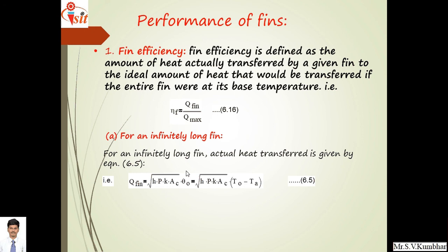So we will see fin efficiency for these three cases: for an infinitely long fin, for a fin when its tip is insulated, and third, for a fin when its tip will directly transfer heat through convection.